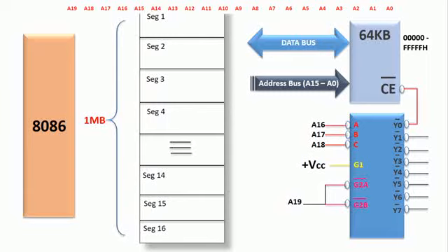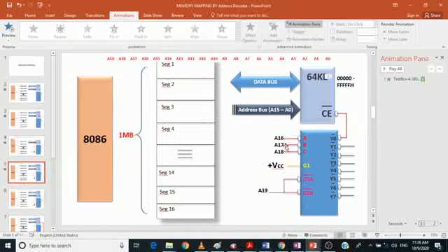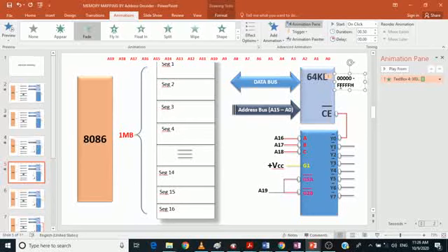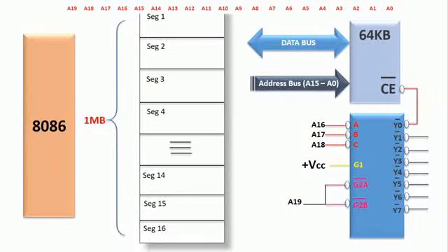This is the address space. Sorry, there are 5 F's, right? Sorry, it is not 5 F's actually, it is only 4 F's. So the address range is 5 zeros to 0FFFFh. Are we clear? So for this particular interfacing diagram, this memory device is mapped into the first segment.